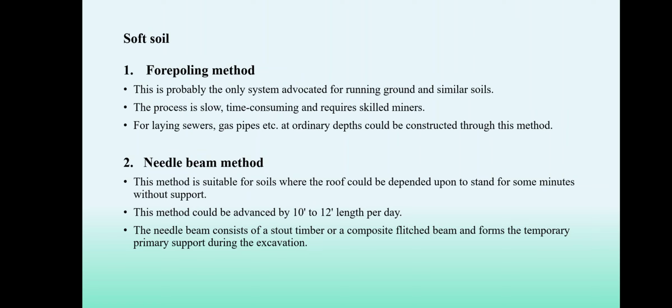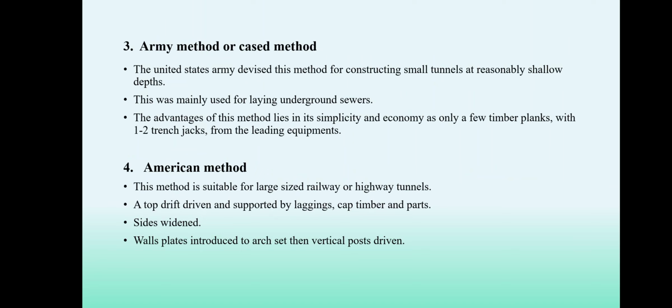Needle beam method. This method is suitable for soil where the roof could be depended upon to stand for some minutes without support. This method could be advanced by 10 to 12 feet of length per day. The needle beam consists of a stout timber or a composite fabricated beam and forms the temporary primary support during the excavation.